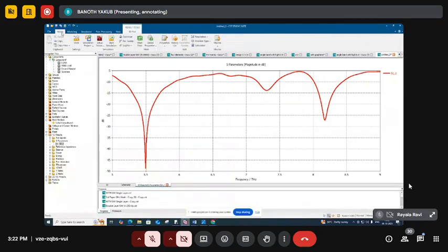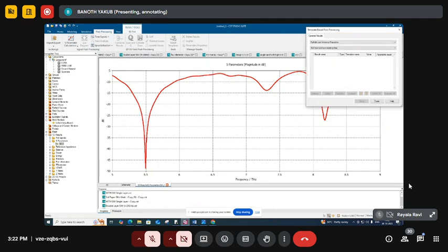So now we can see how to check the axial ratio values, whether we matched or not. For that purpose, go to the post processing result templates. Is that option for axial ratio values visible? Okay. So here are the general results: you can go to the far field result properties, 2D, 3D field results, far field and antenna properties, filter analysis, general 1D, and S parameter. All things will be shown here.